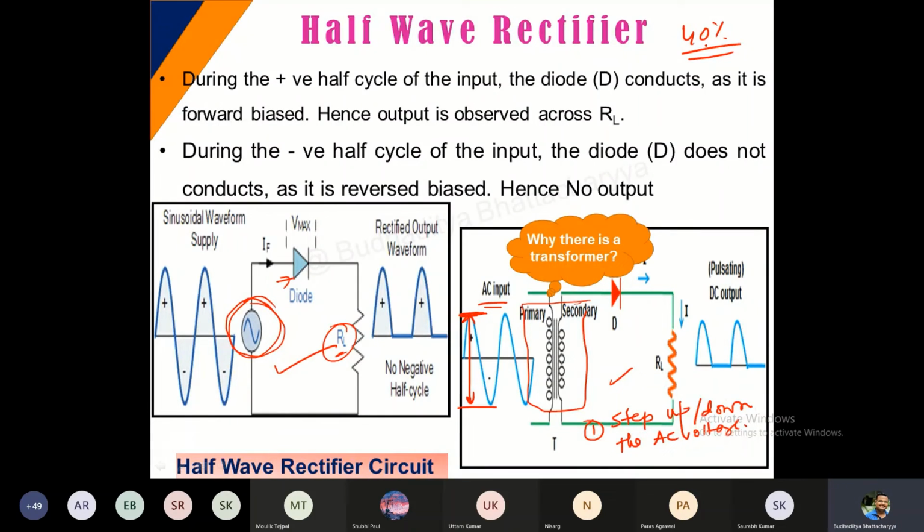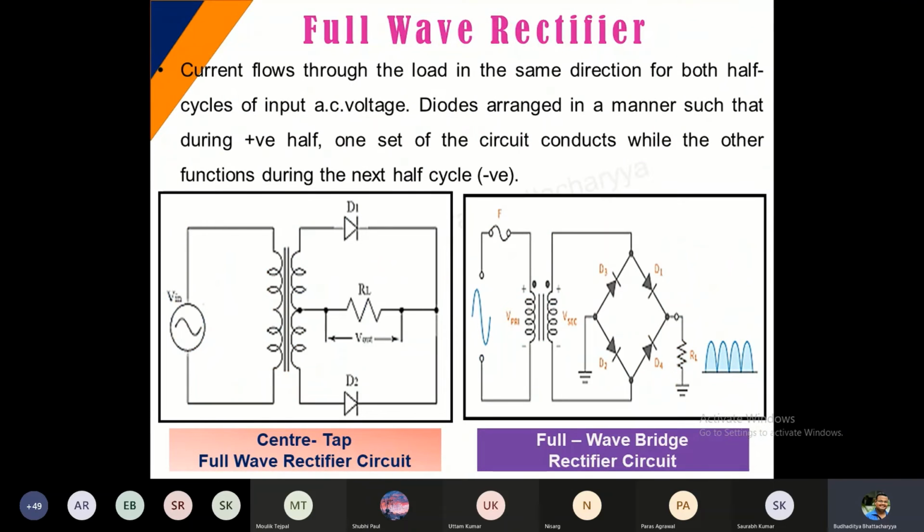All right. So that is done by the full wave rectification process. If you observe here in this particular example, this is a full wave rectification. So what is exactly full wave, as opposed to half wave? It's basically if we design a system such that there are two half waves connected together, then we are assuming that one part of the circuit will work for one half cycle and the second part of the circuit will work for the second half cycle. Then it will be fine.